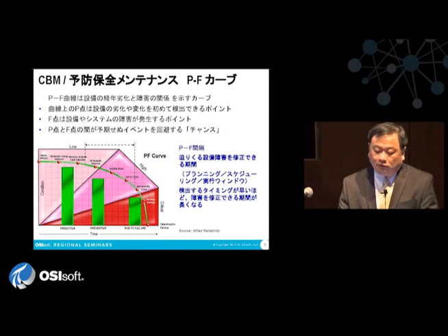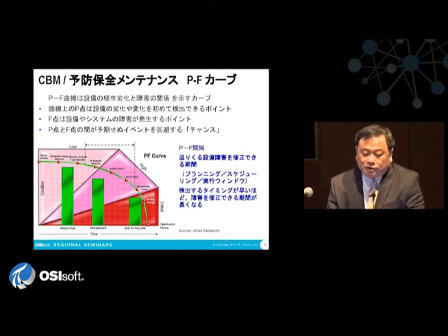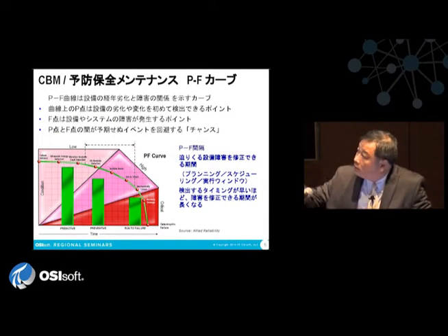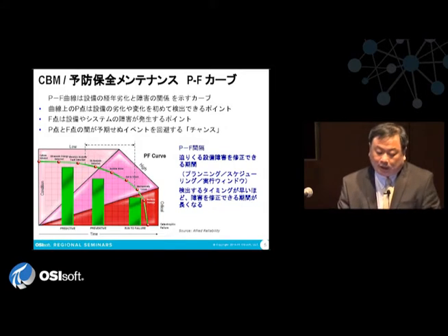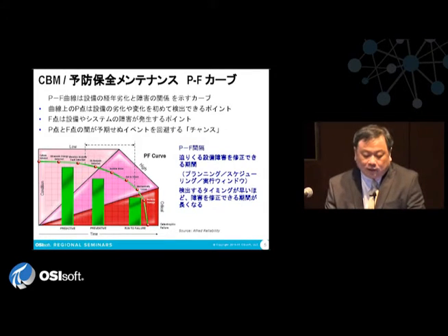Every system or piece of equipment has something that can be detected when its performance is degrading. It could be a slight change in temperature, a high vibration, a change in amps. The P point on the curve represents the time that change is detected.